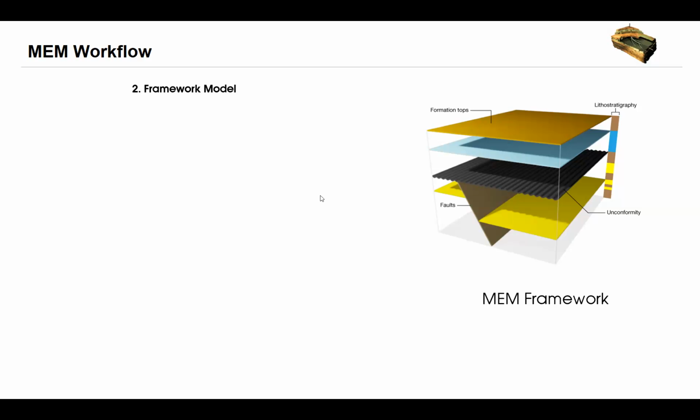We call it the gradient. We can use a hydrostatic vertical gradient or a lithostatic gradient. If there are no big changes in your tectonic setting, present-day tectonic setting, you can use a 1 psi per foot lithostatic gradient to calibrate your vertical overburden stress. It is in general the case.